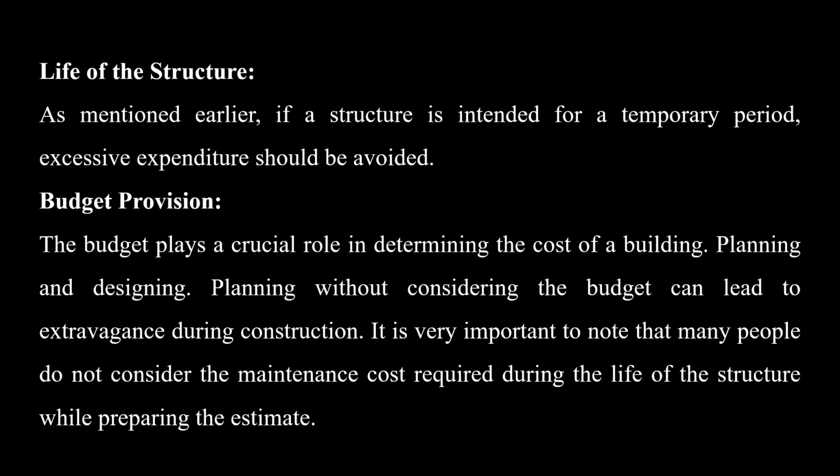Life of the structure. As mentioned earlier, if a structure is intended for a temporary period, excessive expenditure should be avoided. Budget provision. The budget plays a crucial role in determining the cost of a building. Planning without considering the budget can lead to extravagance during construction. It is very important to note that many people do not consider the maintenance cost required during the life of the structure while preparing the estimate. So you should consider the maintenance cost also in the estimate to have economy in the future of the building.